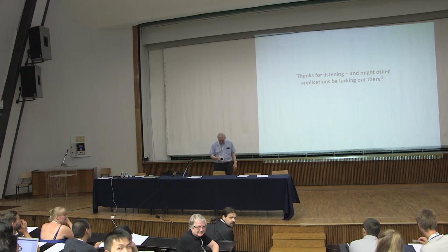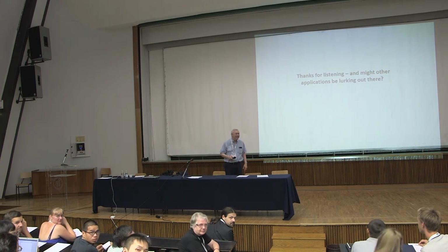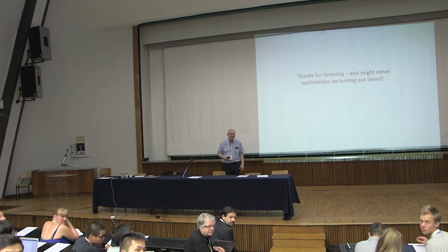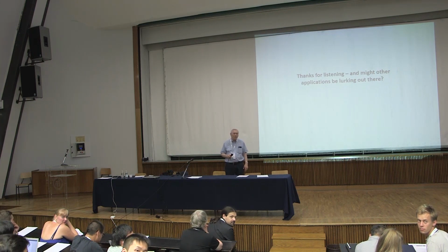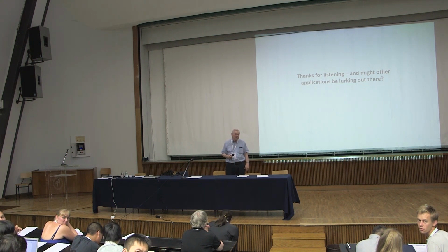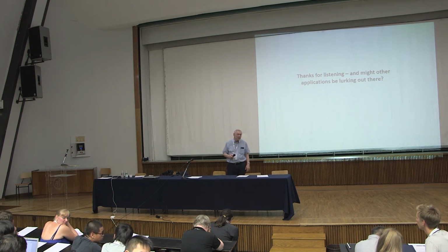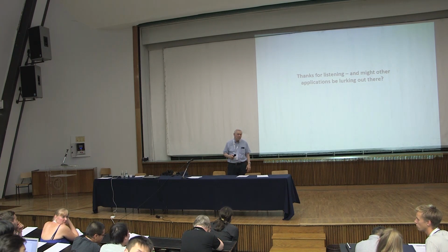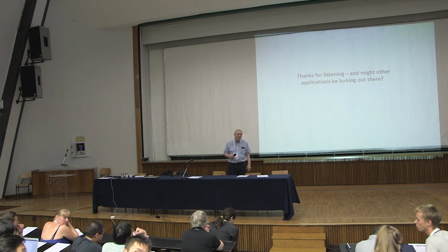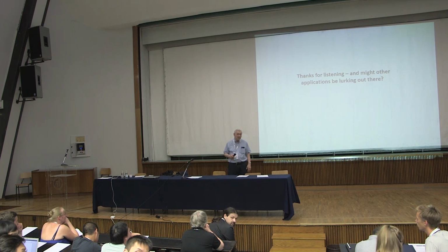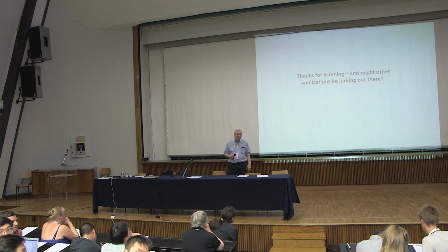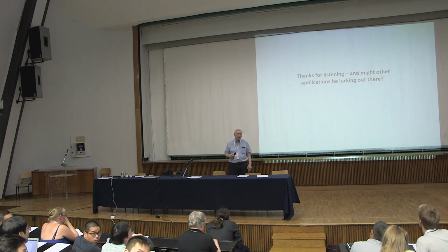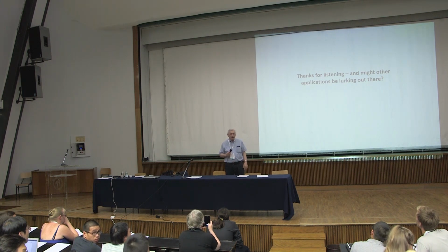Professor Rice? Yes. I have a question regarding failure of single crystals, where the dislocation interaction with the fracture is not dependent on the bulk, but starts from the surface. And all your theories have always worked with the plane strain case. So how can you map your results to a realistic single crystal where the fracture will start at the surface because of dislocations starting from the surface rather than the bulk? Any comments there?